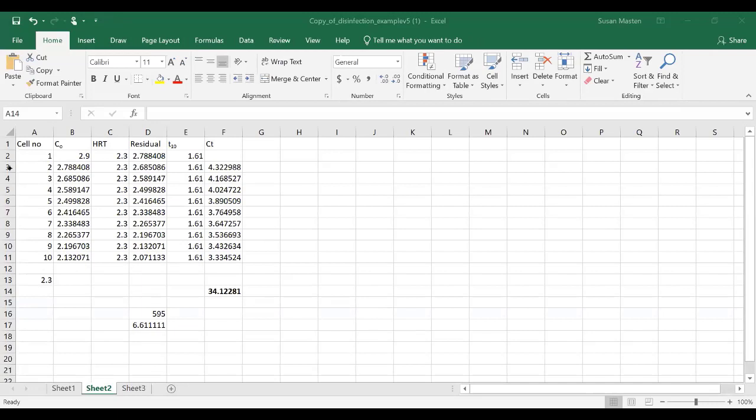I'm going to start here with going back to the 2.5 milligrams per liter. So that was the dose in the initial cell, so in cell 1. Now, cell 1 would have the diffuser in it, so that cell does not give us any credit. So notice there's nothing in this cell here for CT because we get no credit for any cell where there's a diffuser. We calculate the residual using the second order rate constant that was provided and the equation that I just gave you.